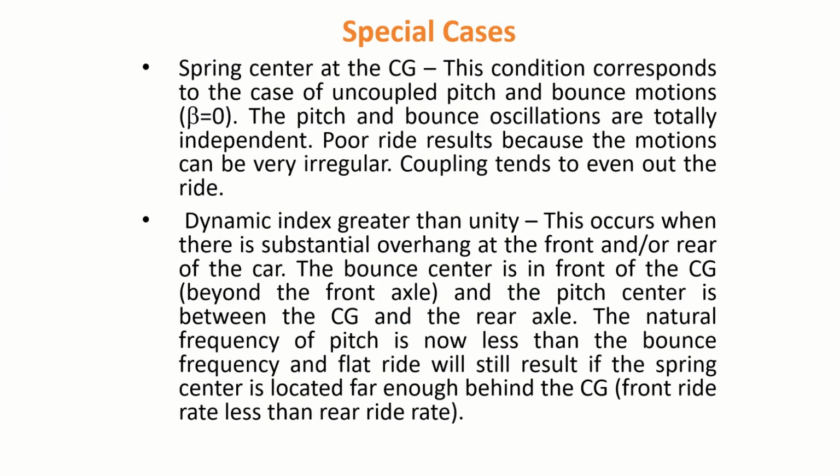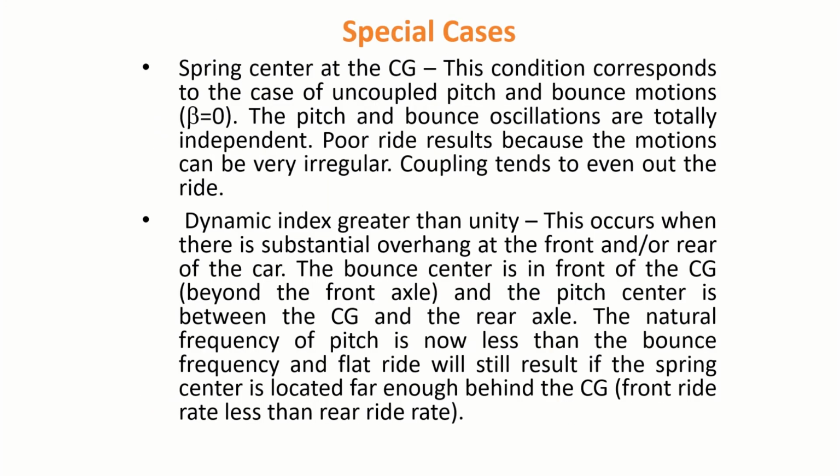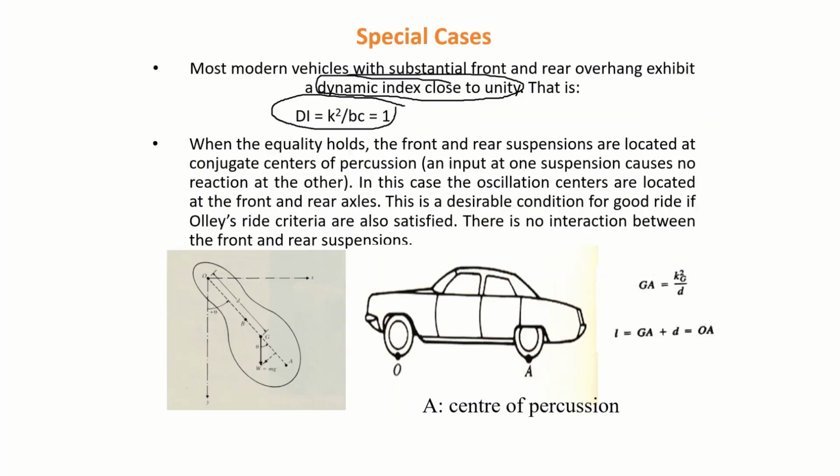So this is the meaning of these parts. In summary, design the system in such a way that roll frequency, pitch frequency and bounce frequency should all be less than or equal to 1.3 hertz. That is the main thing.